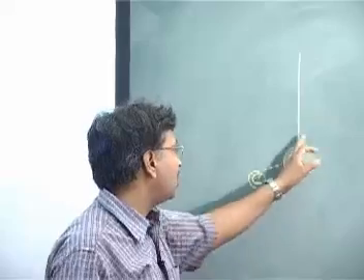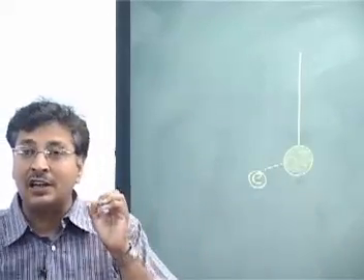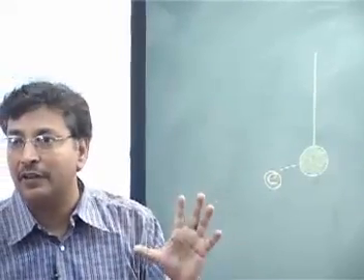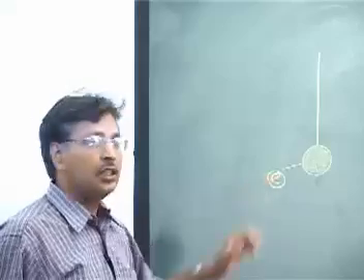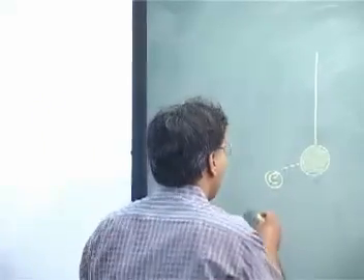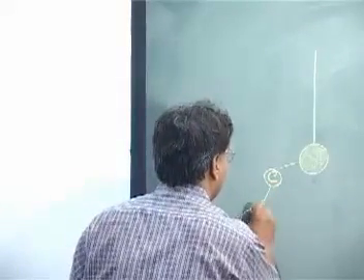Once these stray electrons see the negative charge, they are accelerated away from the electrode. They want to run away because they have the same charge. In the process this acceleration is so much that they hit the gas particles.